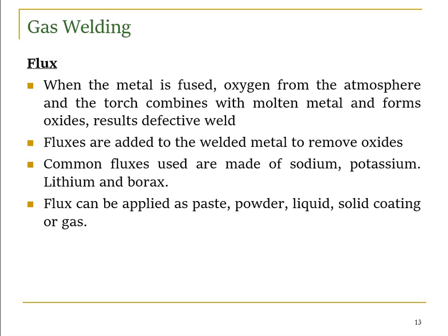The atmosphere has oxygen, so it will form oxides, right? This oxidation is very dangerous. It will create porosity and a defective weld. So in order to avoid this, we use flux.